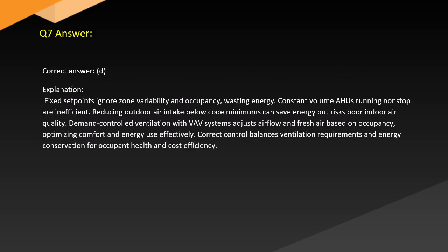Answer. Correct answer: D. Explanation. Fixed set points ignore zone variability and occupancy, wasting energy. Constant volume air handlers running non-stop are inefficient. Reducing outdoor air intake below code minimums can save energy but risks poor indoor air quality.